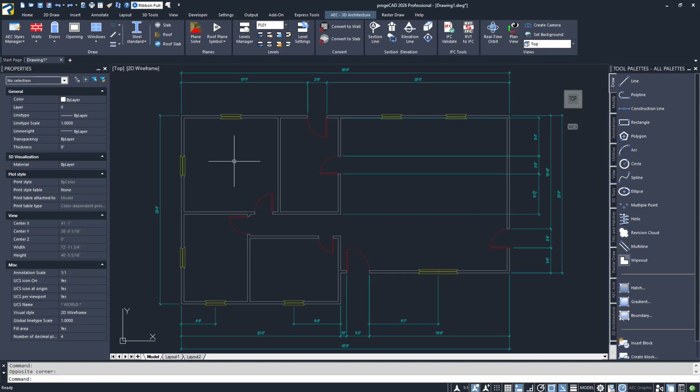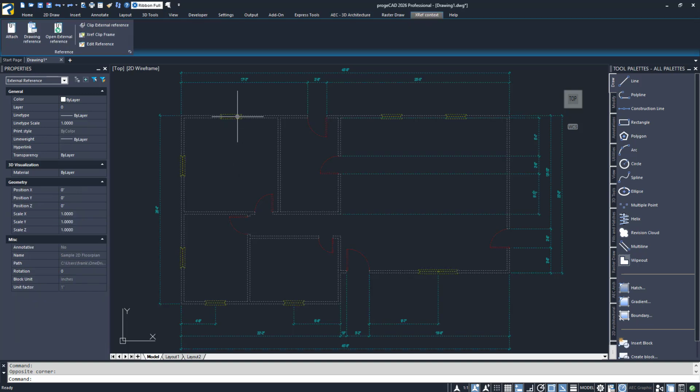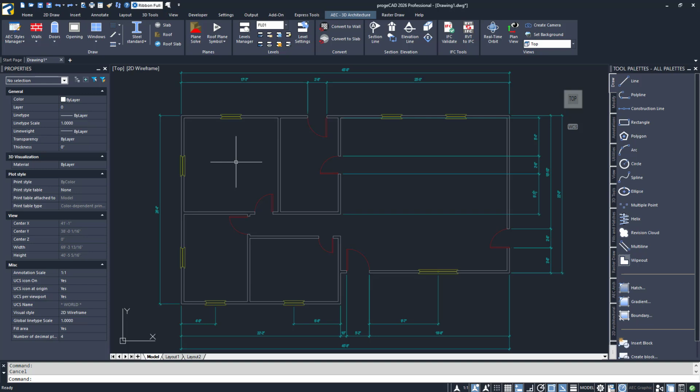For this video, I'll again be using a new drawing, but instead of being totally blank, I've attached a very simple 2D floor plan drawing as an external reference. Of course, you may work from a physical paper drawing, a sketch, or just refer to another drawing file for dimensional information. This is but one method, but it will allow me to snap to it. As an XREF, it is faded a bit, and it provides an easy way for me to remove it when I'm done.